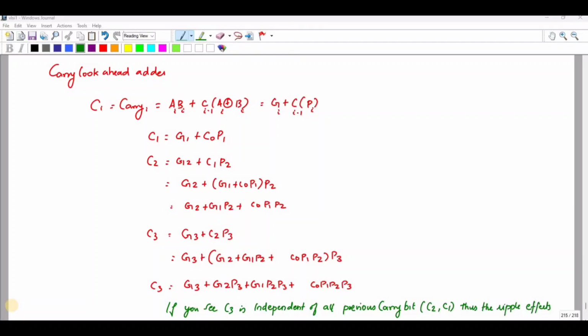In this video we are going to discuss the carry look-ahead adder. While designing a fast adder, it is essential to get around the rippling effect of the carry that is present in one form or another in both the carry bypass and carry select adders. The carry look-ahead adder offers a way of eliminating this rippling effect.